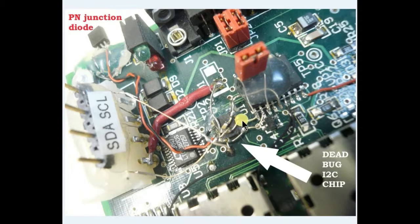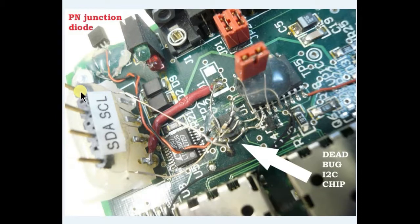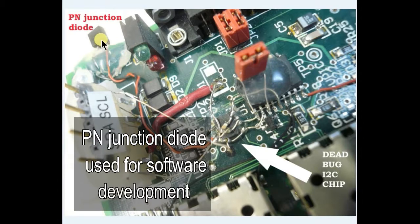We have the clock signals and the data signals coming off to an external port here, so I can monitor it with a scope. Then to emulate the diode embedded in the ASIC, I have a PN junction hanging out here.